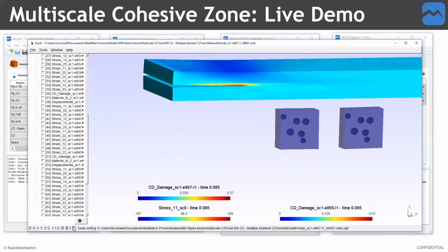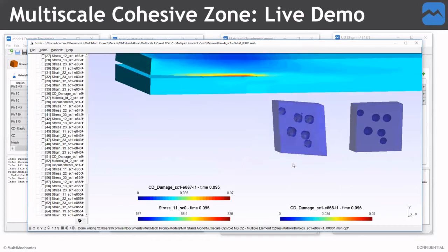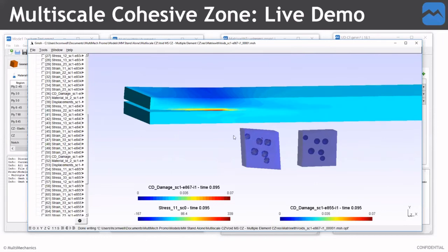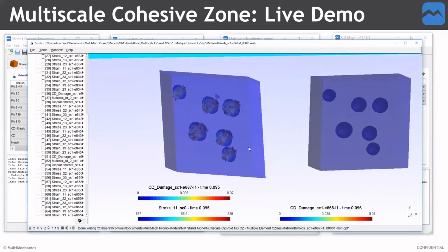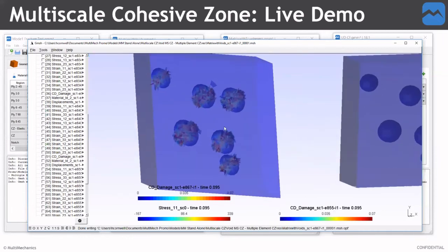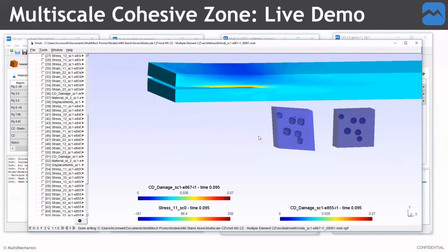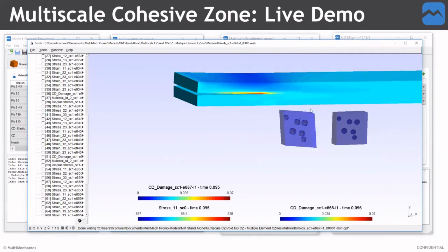We'll do another example of this RVE. We see how the damage passes through, and then the stiffness is reduced and the crack passes through. You see this example of how the crack passes through with the different microstructures. And this is valuable because you get to see exactly how it fails. You notice how with all these different RVEs there are slightly different shear and tensile strains, so you start to see how things will start to fail. So you can start designing your adhesive or your interlaminar region accordingly based off of what you see going on in these results.